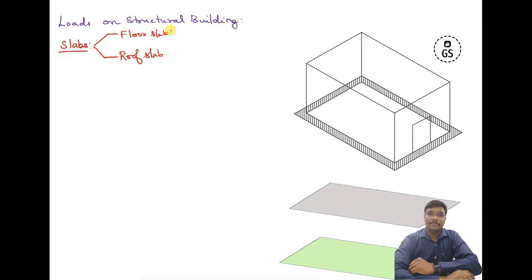In both roof slabs and floor slab, we apply a DPC layer. That is called damp proof course. We apply this damp proof course to protect against rainwater or groundwater penetration in the foundation layers. That is to resist the moisture content. So we need to protect the roof slabs. In such case, the thickness of the DPC layer will vary.